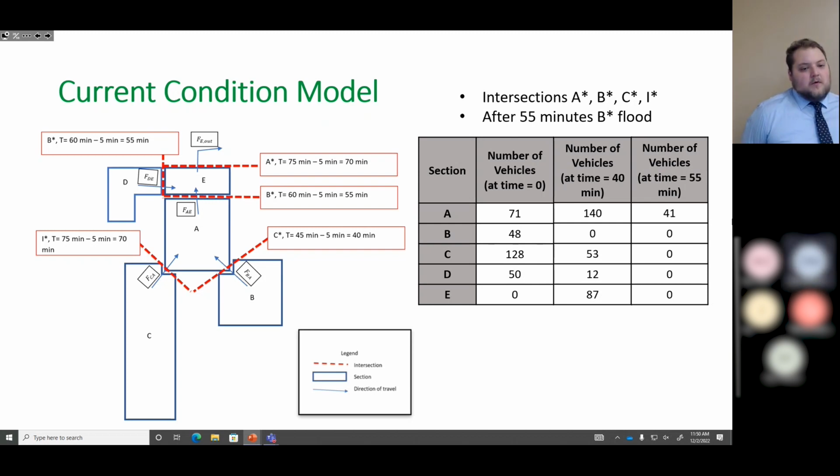So that is a good point. We never thought to think after how long they're going to be stuck with the flooding. Based on my model, 24-hour duration, it still was over the roadway a good amount, so I'm not sure what would be past that point. So your model was only 1D, right? Yeah. It was a steady flow condition. You need an unsteady flow model to see, okay, it comes up, it comes down.